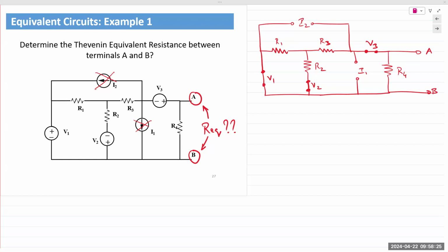So if you think back to the beginning of chapter 2, if you wish to find Req for any circuit, then we start at the farthest end. You can use any technique, right? The technique I showed in class, the two horizontal lines, parallel lines, or if you're familiar with your own techniques, you can go ahead and use that. But if you start at the farthest end, we see R1 and R2 are in parallel. So I'm going to write R1 and R2 in parallel, which is then in series with R3, and which is then parallel with R4.